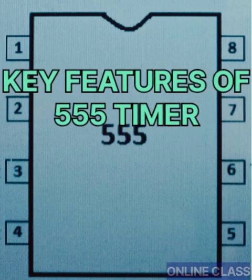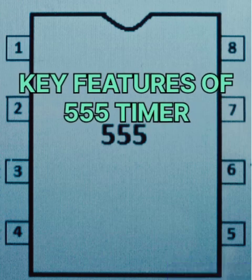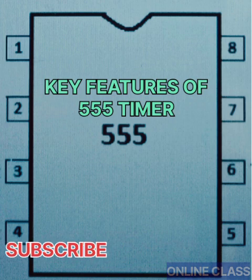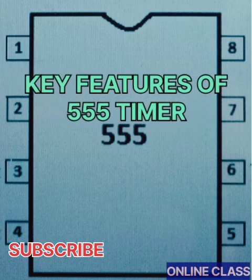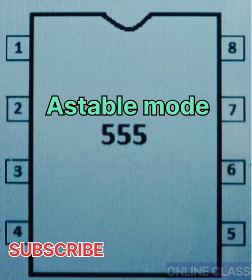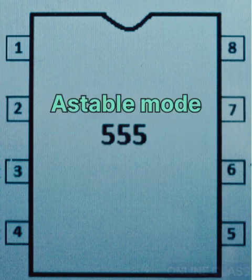Number 6. The duty cycle of the timer can be adjusted. Number 7. The maximum power dissipation for each package is 600 milliwatt and its trigger, pulse and reset inputs are compatible with logic levels. The 555 timer integrated circuit typically functions in three modes: astable mode, monostable mode and bistable mode.